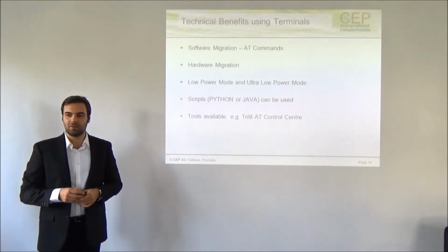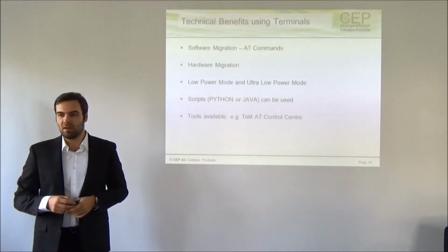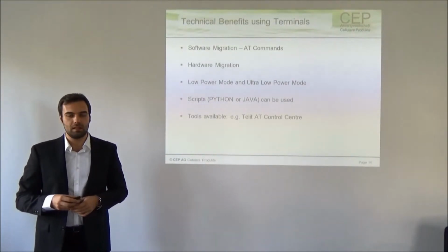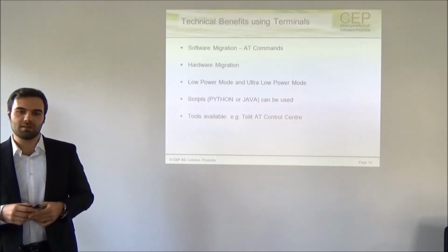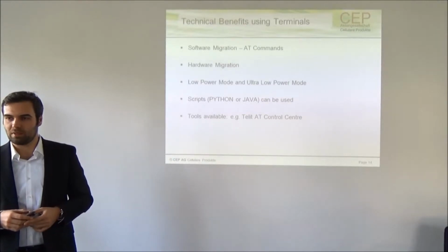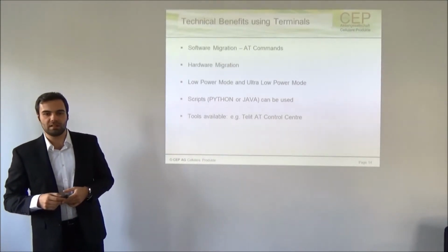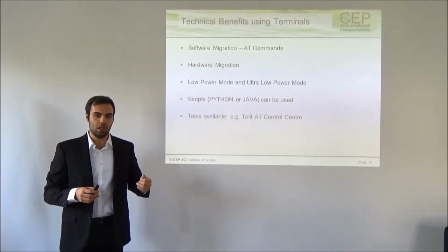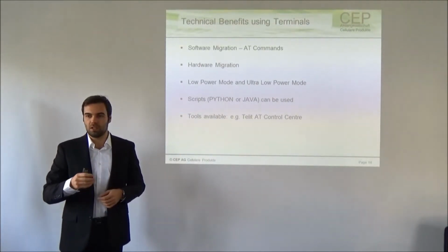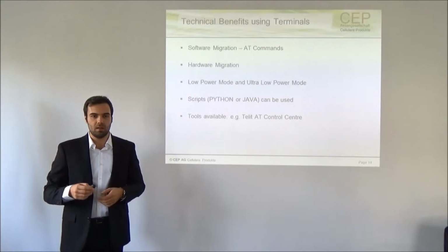The technical benefit of using a terminal is basically that we have, let's say, an easy software migration path, because it's basically built up on AT commands. So these terminals are communicating with AT commands. So when you have once implemented a set of AT commands for one terminal, then you can basically use it, for example, if you have another application where you need another technology, for example, you want to go from 2G to 3G, then you can use a 3G terminal and don't have to implement all the AT commands from the beginning.